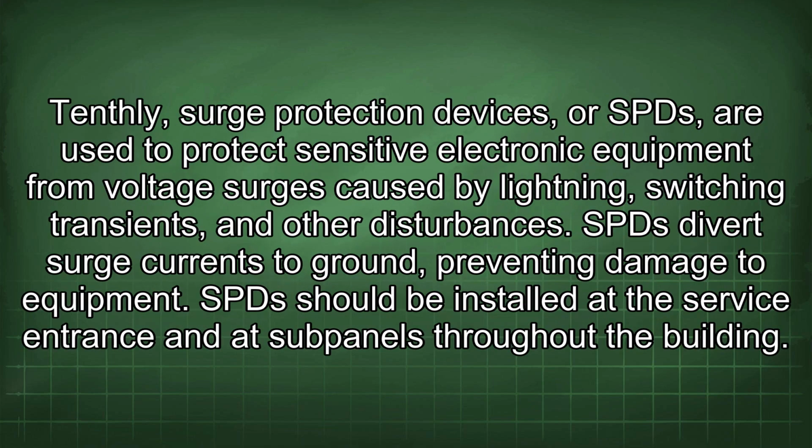Tenthly, surge protection devices, or SPDs, are used to protect sensitive electronic equipment from voltage surges caused by lightning, switching transients, and other disturbances. SPDs divert surge currents to ground, preventing damage to equipment. SPDs should be installed at the service entrance and at subpanels throughout the building.